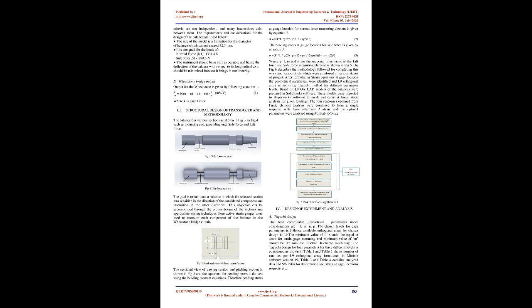2. Shape optimization of drag force element carried out. Rectangular parallelepiped converted into concave-shaped flexure, and computational results showed that there is a considerable increase in the outputs for concave-shaped flexure with marginal increase in the interactions. 3. Shape optimization of 25 mm internal balance was carried out. The material used for the balance is 17-4 PH stainless steel. Model is prepared in Unigraphics design software and the model imported in HyperMesh software for the meshing and analysis purpose.